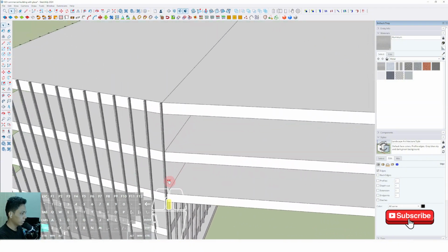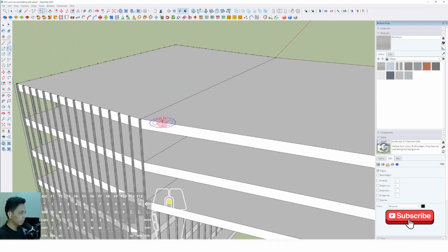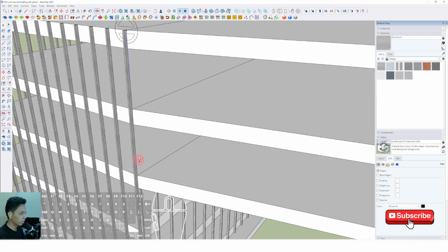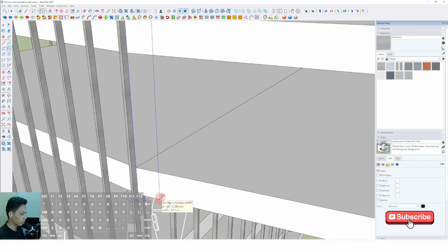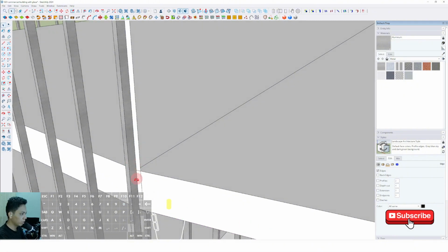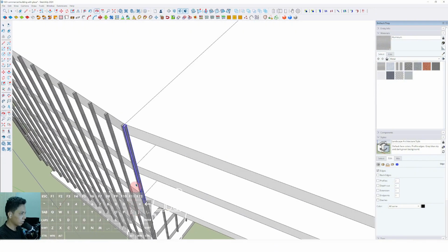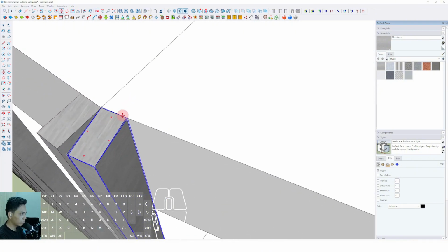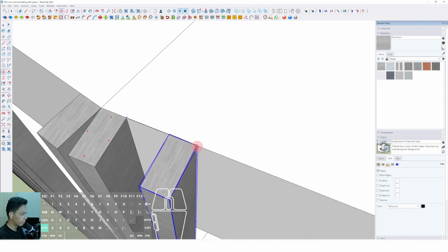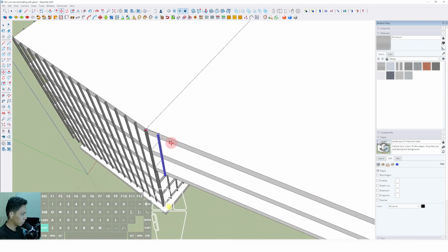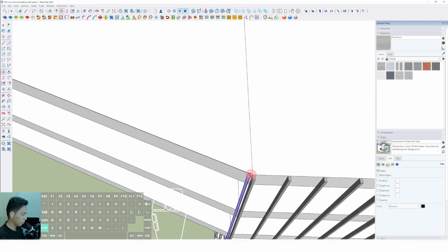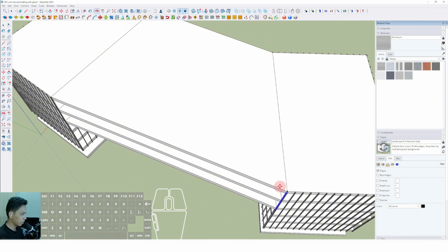Then we have to make the vertical frame again. Click from this position, click to this position, then we can set the height around 100 millimeter. Then we have to push it to the front around 200 millimeter. Triple click, right click and make group, right click and make component, create, select aluminum assignment of the material. Then we can select move, press Ctrl, and place to this appropriate position. Then we can type 30 slash enter.